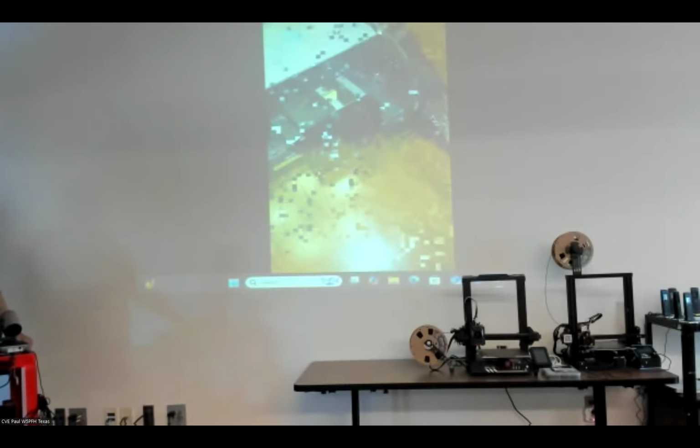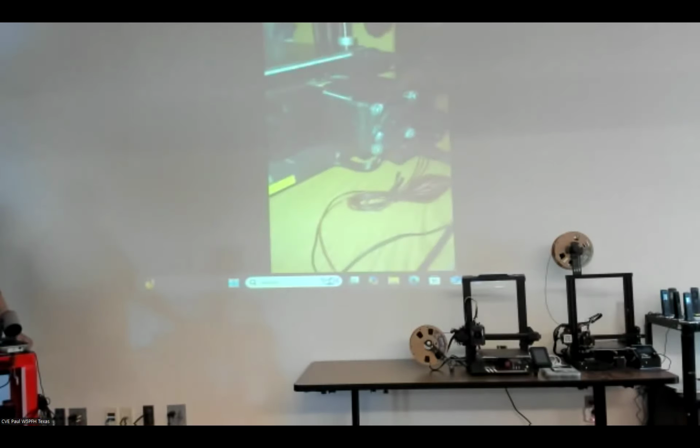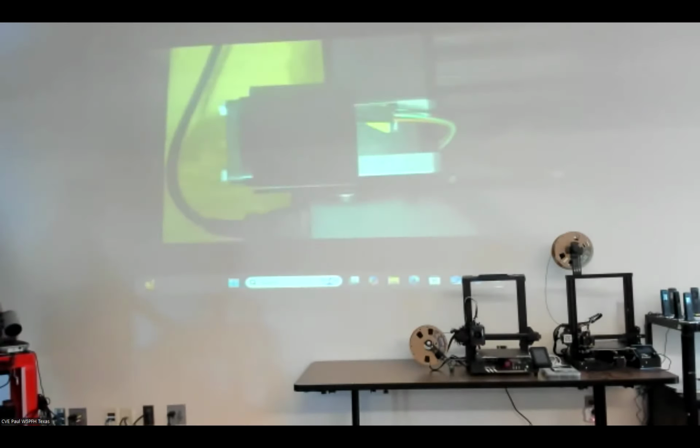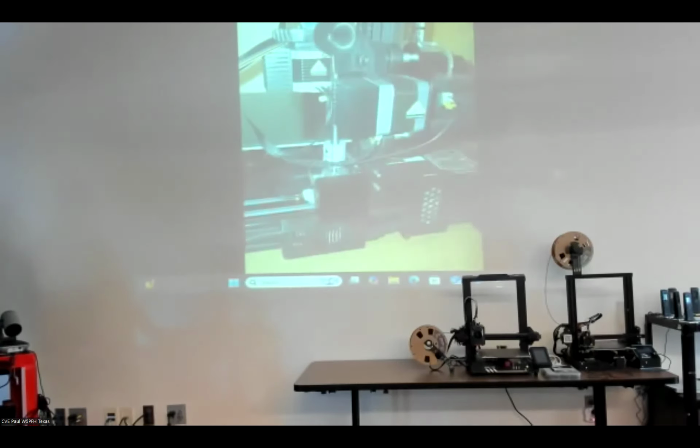What a lot of people don't realize with 3D printers is that pretty much all the filament is hygroscopic. It absorbs moisture. You've got to keep it dry, or dry it. Build a drying cabinet, or keep it in a dry box. I burn through it fast enough when I open one that I typically don't have an issue with it getting waterlogged.